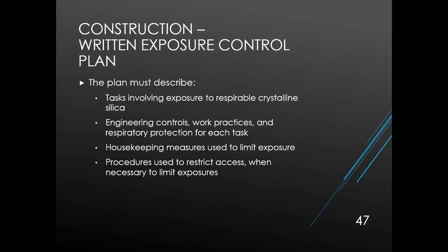For employers that are using either specified exposure control methods or alternative exposure control methods, the employer must have in place a written exposure control plan that addresses a description of the tasks in the workplace that involve exposure to silica, a description of the engineering controls, work practices, and respiratory protection used to limit employee exposure to silica for each task, a description of the housekeeping measures used to limit employee exposure, and a description of the procedures used to restrict access to work areas when necessary to minimize the number of employees exposed to respirable crystalline silica and their level of exposure, including exposures generated by other employers or sole proprietors.